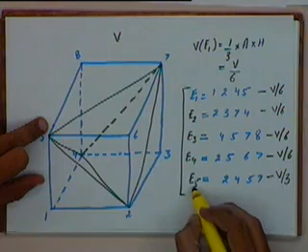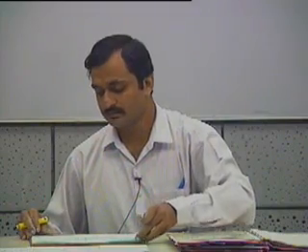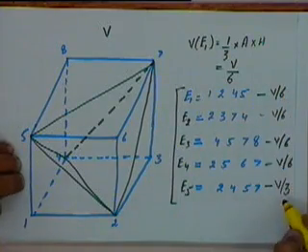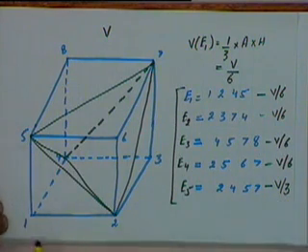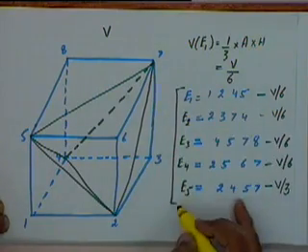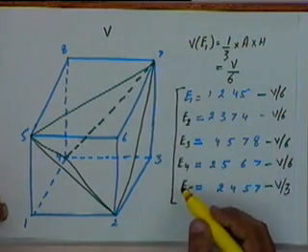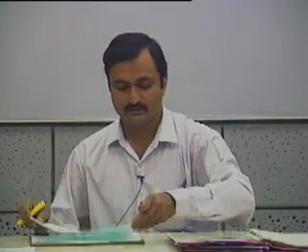So if we cut off the corners, we will have a tetrahedral element in the center, that is this element number 5. And we said that if you look at the volumes of these 5 elements, the first 4 have a volume of V by 6 and the fifth one has a volume of V by 3. And if we want to get elements of the same size, that is, the same volume for all the elements, we can divide it in another way, and that is like this.